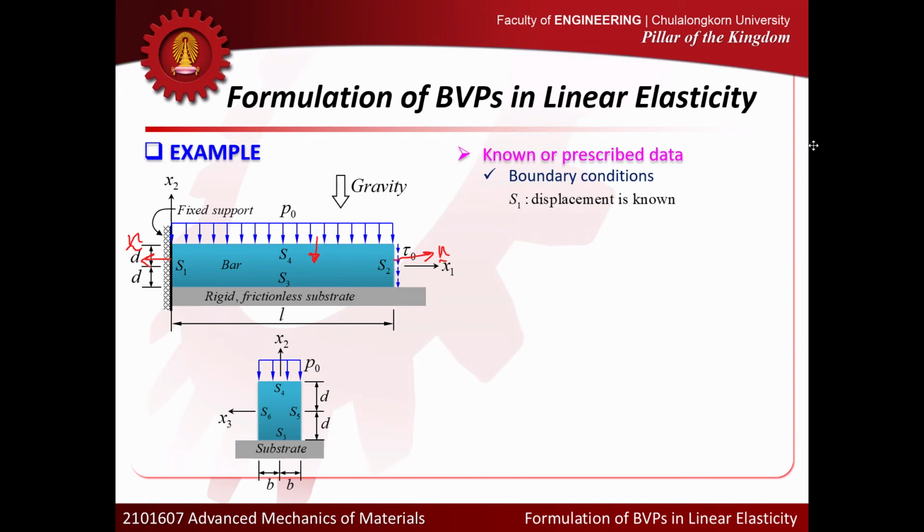That means at every point on the surface S1, the displacement field is equal to 0. So we know U0, the prescribed displacement at part of the boundary, and U0 is simply 0, 0, and 0, because every point on that surface is fully fixed against displacement.